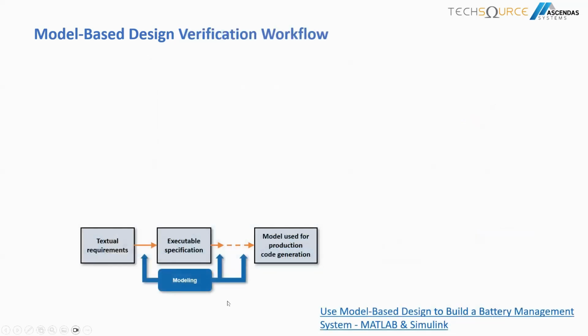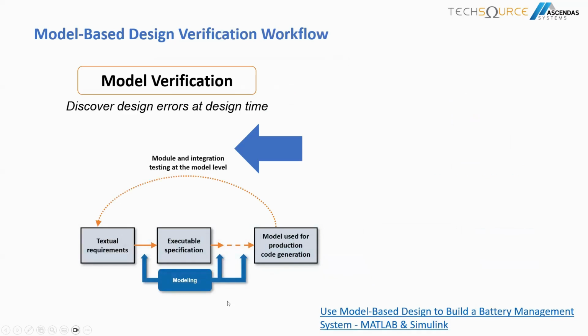In contextual requirements, there's model verification to discover design errors. With model-based design, it happens continuously. So even at the start of your design, you're already doing the testing and performing back-to-back testing. You're working with tools like Simulink Test, Simulink Coverage, and Simulink Design Verifier.